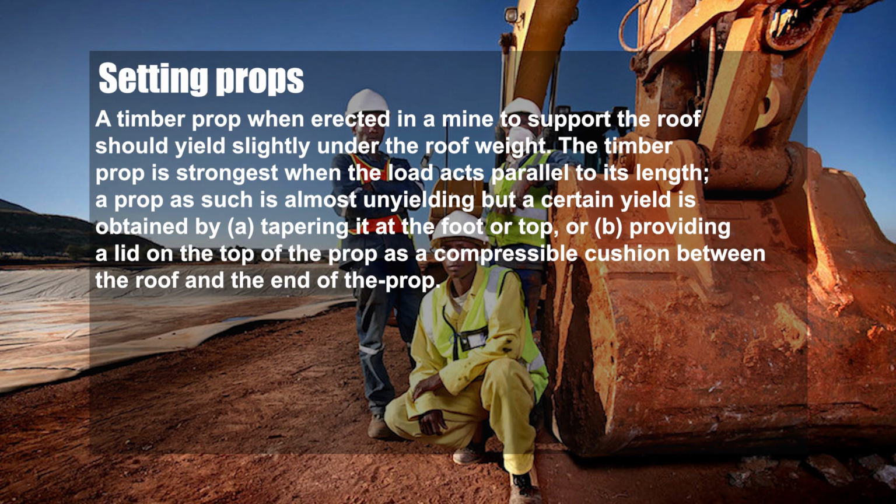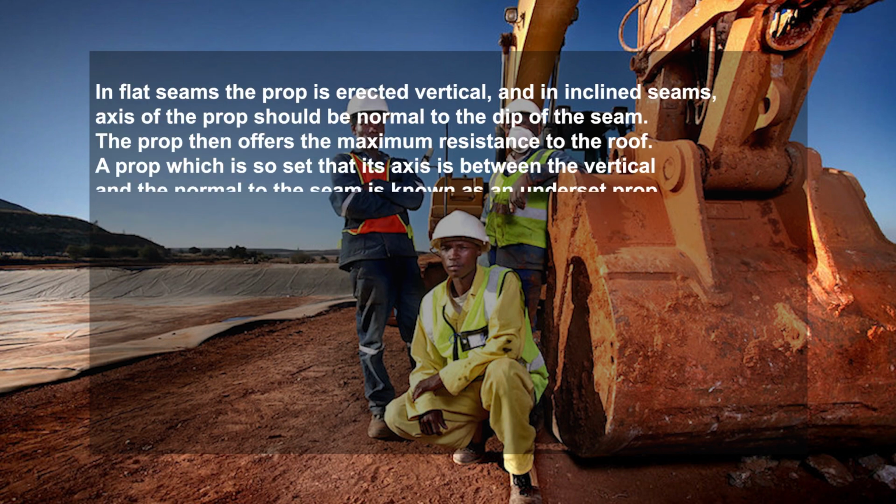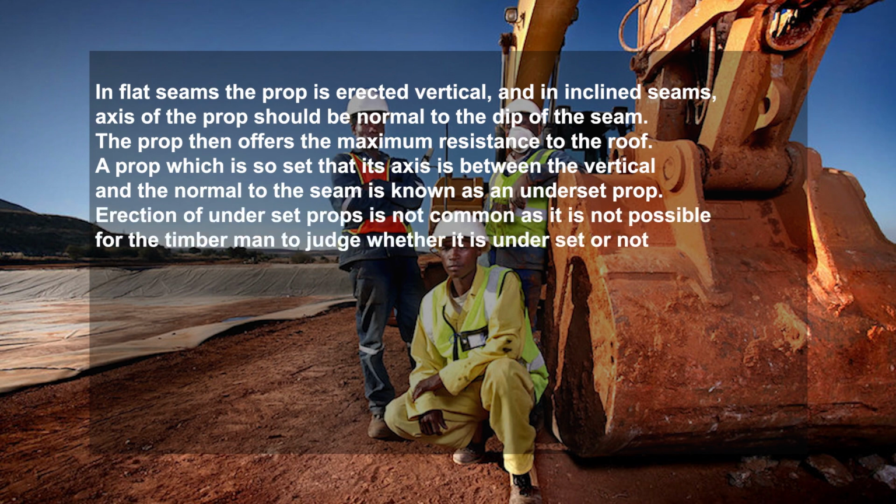end of the prop. In flat seam, the prop is erected vertical, and in inclined seam, the axis of the prop should be normal to the dip of the seam. The prop then offers the maximum resistance to the roof.